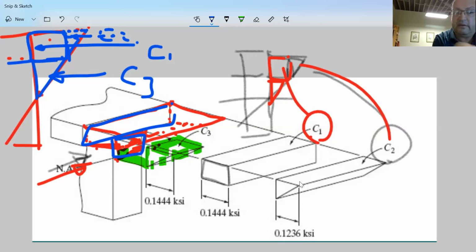So now location of this force from the neutral axis is gonna be 2/3 of this little depth from here to there. And location of this C1 is gonna be from the center of the flange to here. Location of C2, which is right at this triangle on the flange, is gonna be 2/3 of this triangular base plus this little section. If this makes sense to you there.